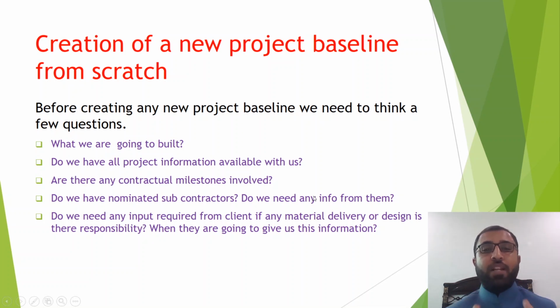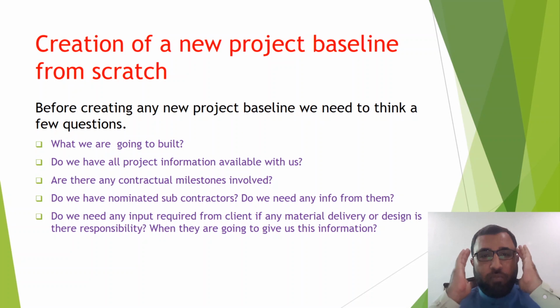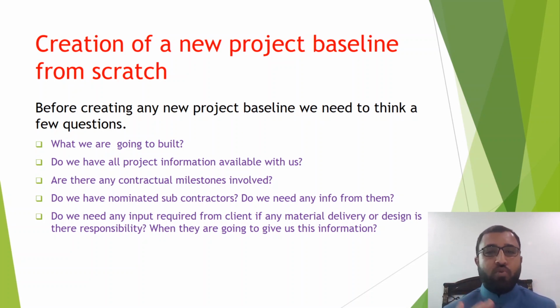So before creating any baseline, you need to gather the data. The first step is to gather the data. Drawings, specification, BOQ, contract. Then you need to think what we are going to build. Okay? All the project should be in your mind. So planning process doesn't start just merely going to P6 and start creating your baseline. No. First, you will have to think from here. The planning starts from your head.